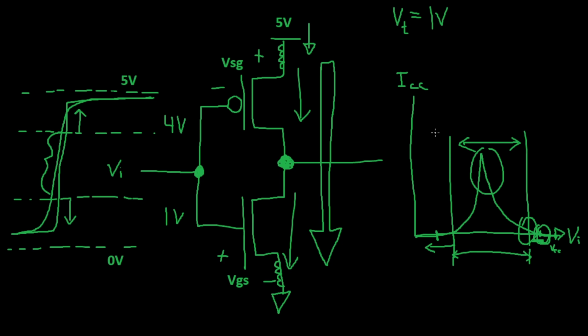Specifically in the case of clock devices like flip-flops and shift registers or counters, you can see those devices act very abnormally, like the clock was being flipped multiple times, even though you can look at your scope shot and see that you've only got one slow edge coming in. What's likely happening is that the device is oscillating internally, and you may be able to see that as some noise at the input. Now let's talk about floating inputs.